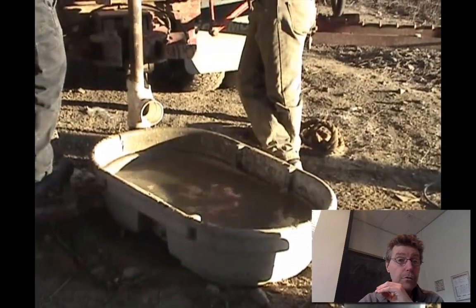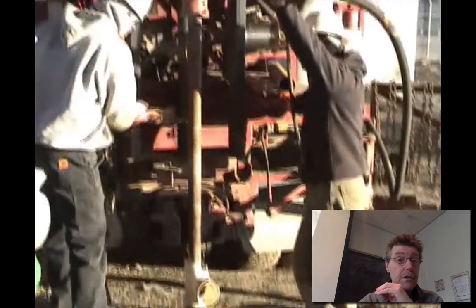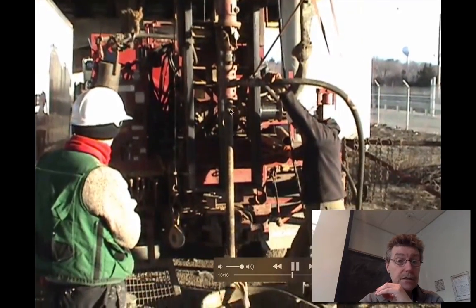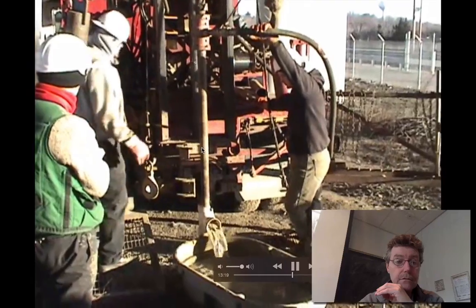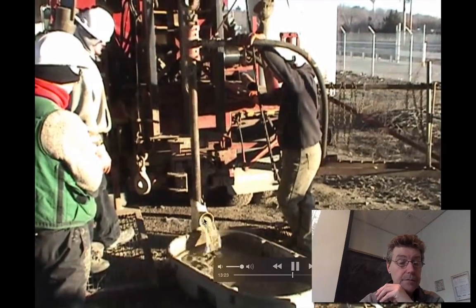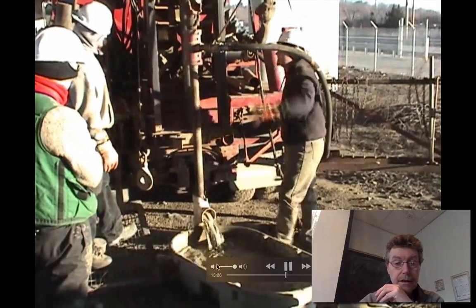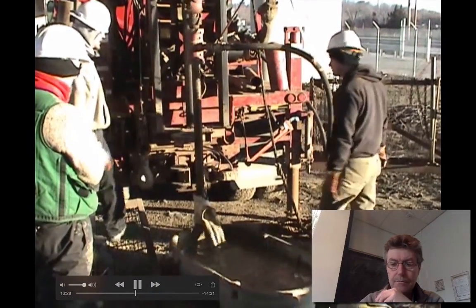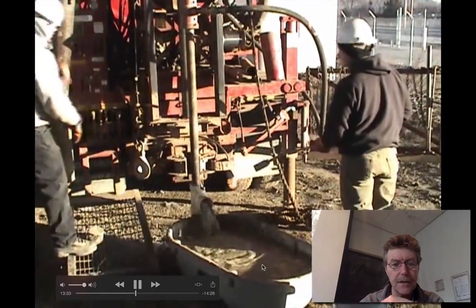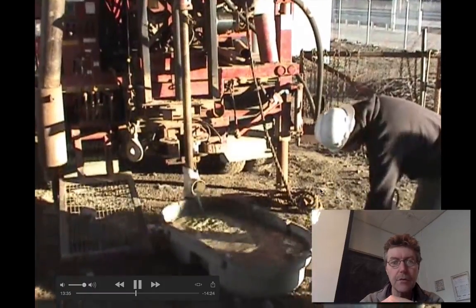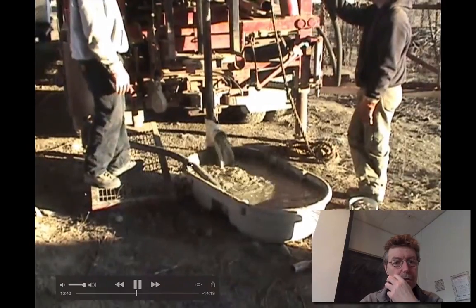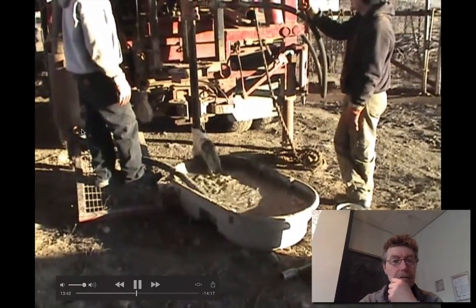And now with that added on the top, they'll couple the whole of the drill string up to the turntable with this connector here. The water goes down the drill string to the bottom of the hole, and then washes the cuttings back up into here. I don't see it here, perhaps it's plumbed in some different way, they'll be taking the water out of here, and it will go back up into the, oh, here it is. This is the suction that's taking the water out of here and back up into the drill string.